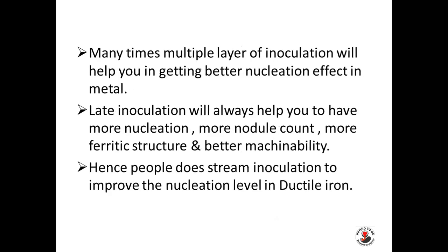Many times, multiple layers of inoculation will help you in getting better nucleation effect in the metal. Late inoculation will always help you to have more nucleation and more nodal count, more ferritic structure, and better machinability. Hence, people do stream inoculation to improve nucleation level in ductile iron.